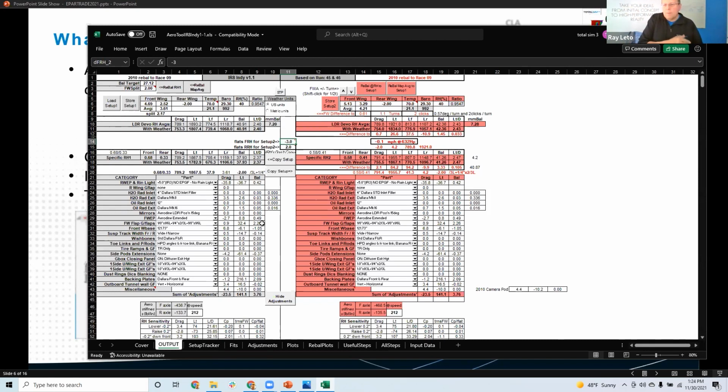And this is what happens at the top end of motorsports all the time. You're watching the telemetry, you're seeing that the aero balance is a little bit off. Okay, we need a half a turn of front wing. How do they know that? That's because they map this out and they understand that to do X% of aero balance, it's this much front wing to do that. They're not guessing. This stuff happens because we've got this data.